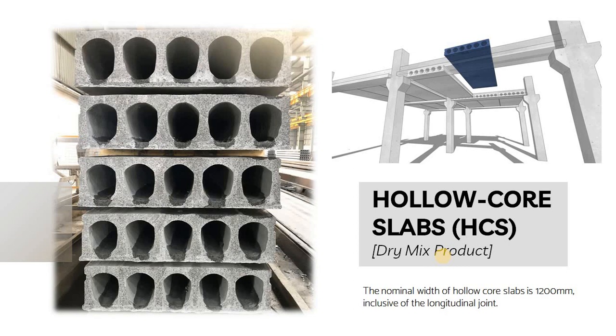If we talk about dry concrete, it is a zero slump concrete. There will be no slump. When the material is prepared, it is prepared as a controlled mix, where there will be water, but at a moisture point only. When we take the material and feel it in hand, a ball can be created using that concrete.